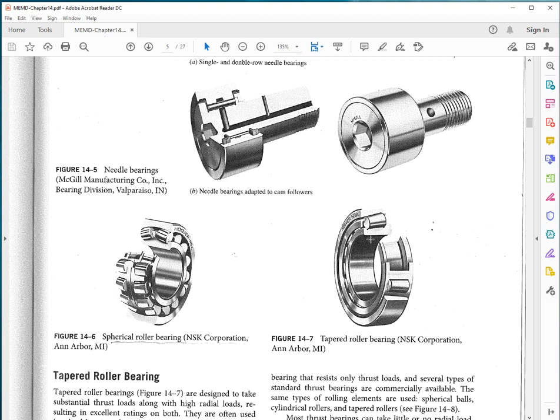They can be separated. That is, the inner race with rolling elements and the cage can be separated from the outer race, and the designer should consider how to adjust and maintain the desired small clearance as the bearing gets put together.